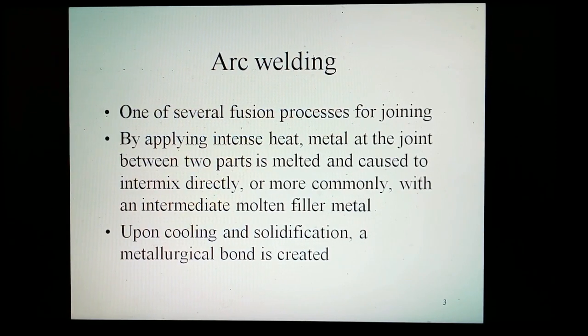Arc welding is one of several fusion processes for joining metals. By applying intense heat, metal at the joint between two parts is melted and caused to intermix directly, or more commonly, with an intermediate molten filler metal. Upon cooling and solidification, a metallurgical bond is created.